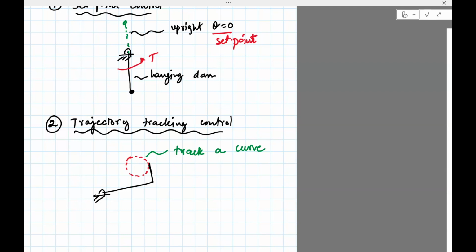When we did the trajectory tracking, we really did not do the tracking. What we did was just set the position of the angles based on the inverse kinematics. We really did not consider the dynamics of the manipulator. So for example, if this is in the vertical plane, then gravity is going to affect your ability to draw the circle. So you can't just set the positions because it's not going to do what you wanted, because it has to work against the mass, inertia, gravity, and so on.